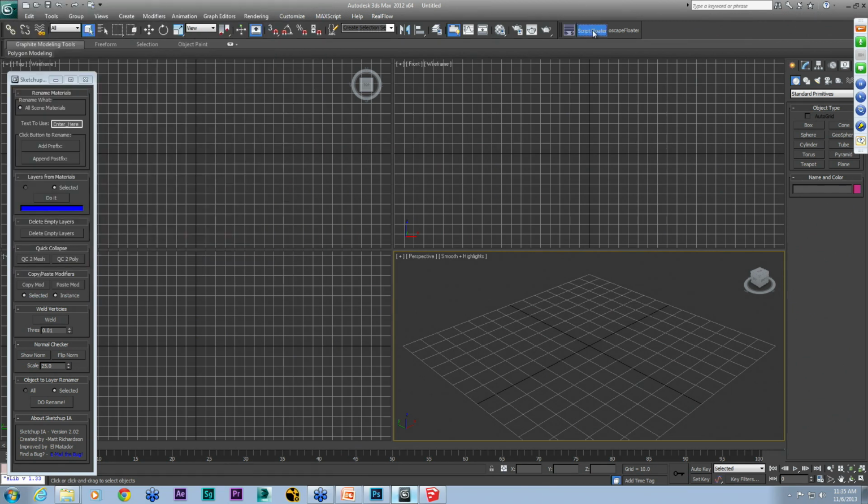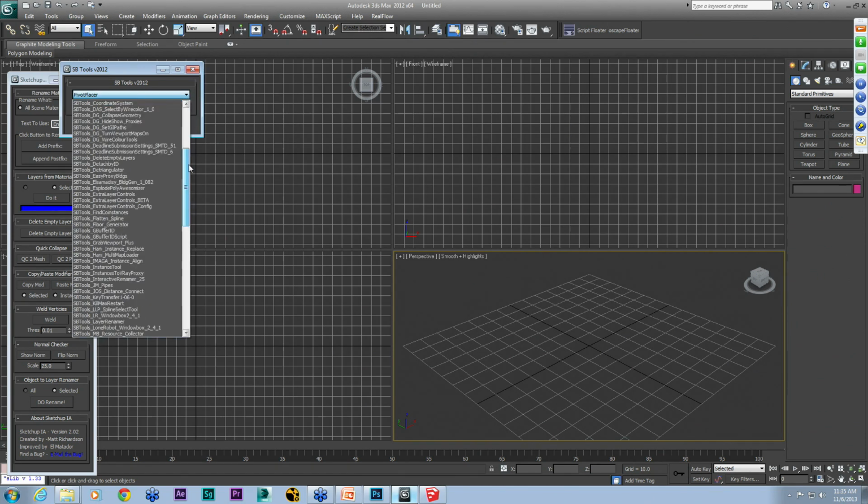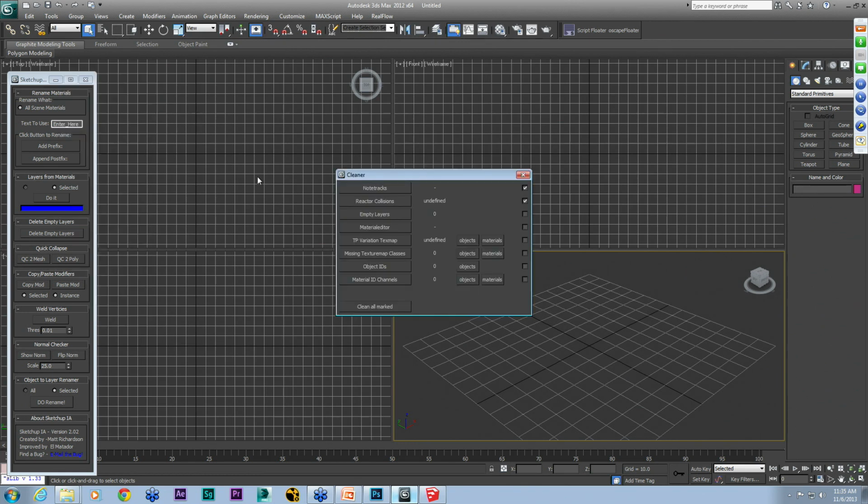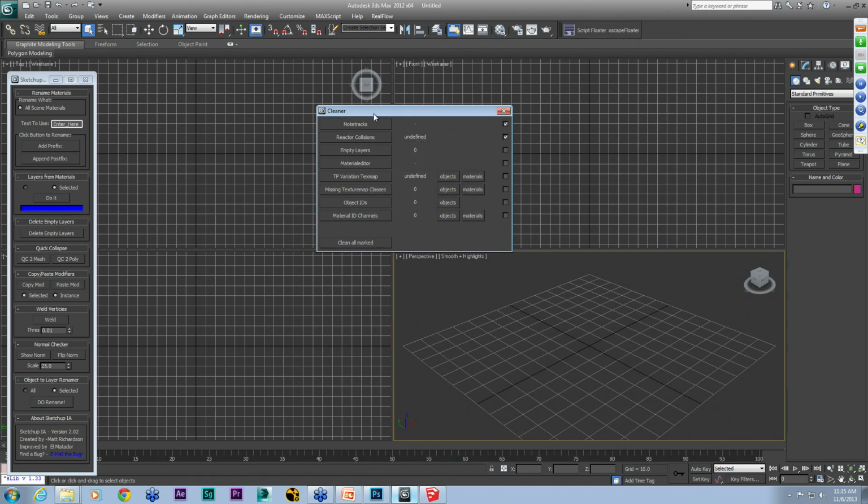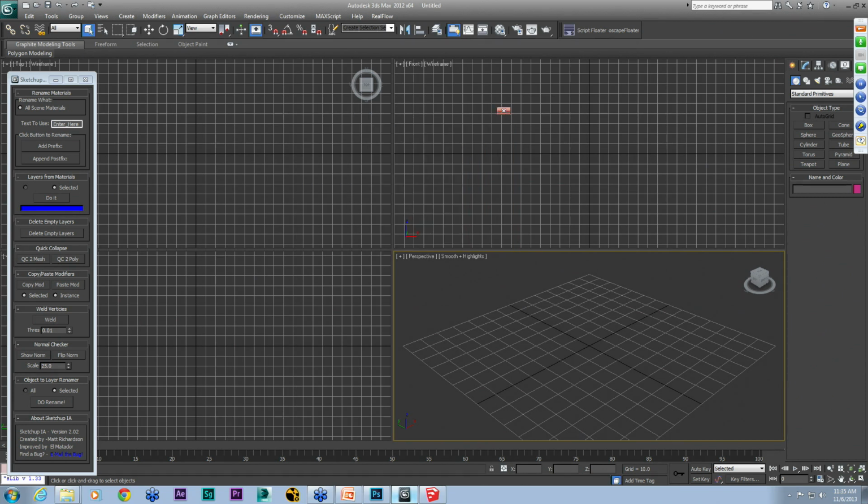There's a Max scene cleaner on the web, and we've also developed some scripts internally that allow you to clean out different things, like those empty nodes and empty hierarchies. Essentially, we developed a script that will take a dummy, assign it to that hierarchy, and then detach the hierarchy from the geometry, and then delete that empty node. So that'll clean out all those things. And that's the only real problem we've had with Revit, other than bringing it in.